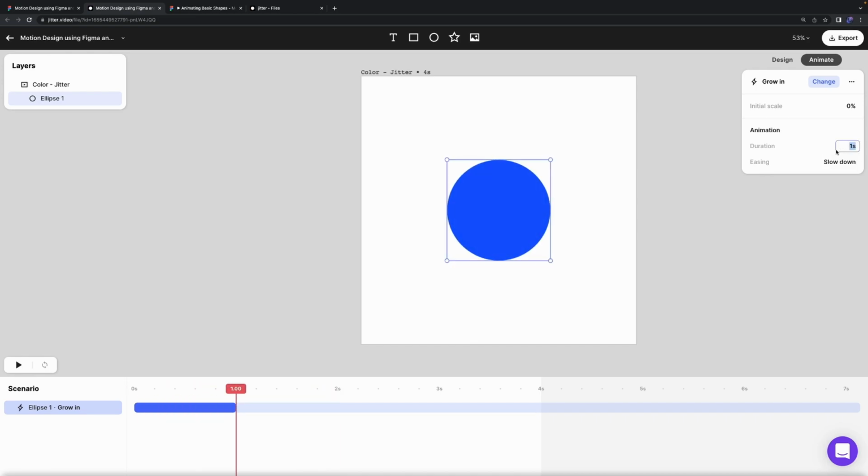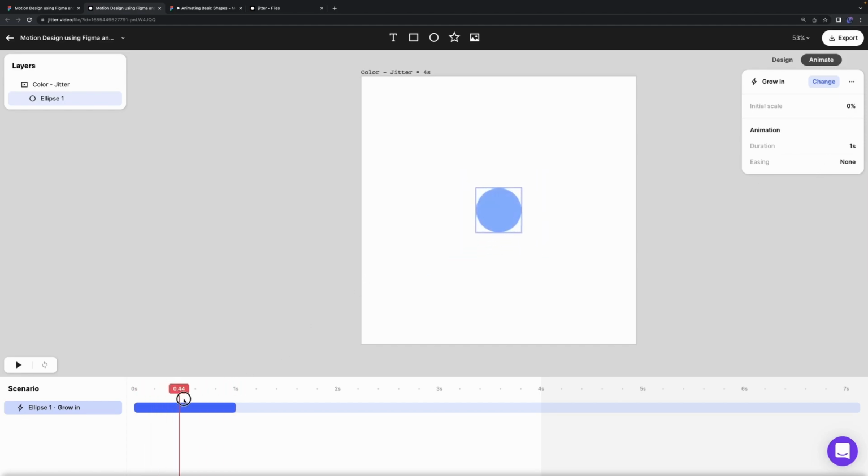And then we can change the type of easing. So this is linear, so it just goes straight. And this is how animation curves work. You have an ease in and an ease out. So like a natural one, we can see this kind of curve. It's kind of like a speed ramp basically. So with none, we're at constant speed. So your animation will operate very mathematically correct, calculated. It's all linear, right? But you can see there's a little graph.